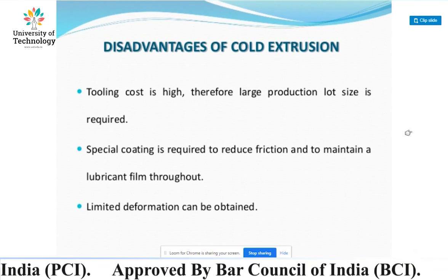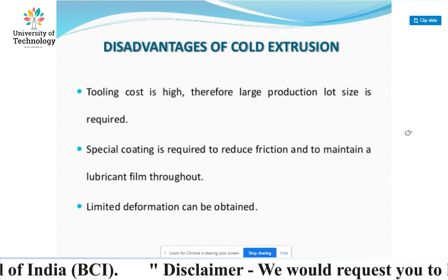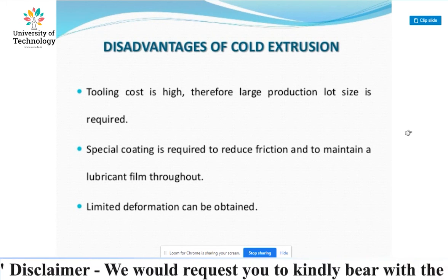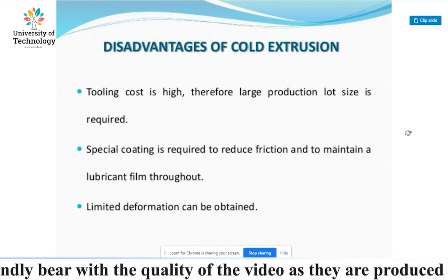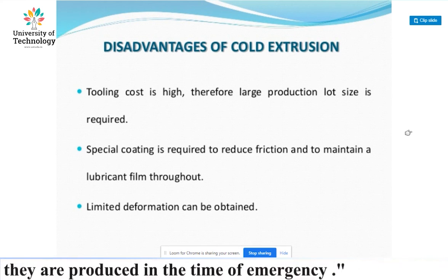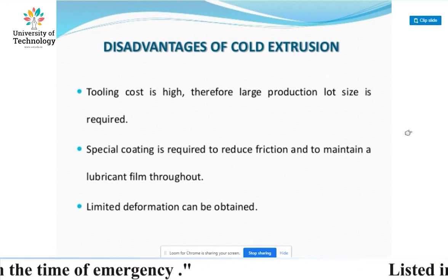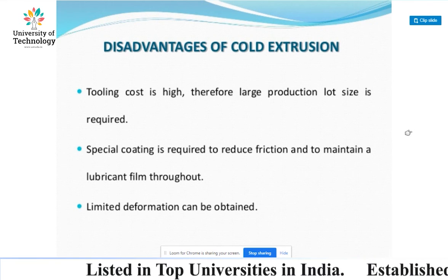Disadvantage of cold extrusion is the tooling cost is high, therefore a large production lot size is required. Special coating is required to reduce friction and to maintain a lubricant film throughout the cold extrusion. Limited deformation can be obtained in the cold extrusion process.